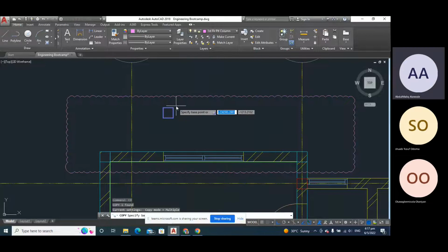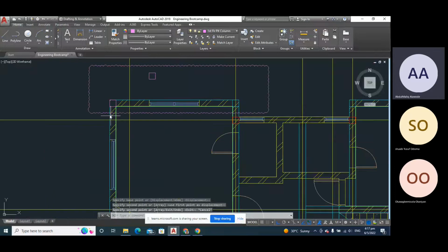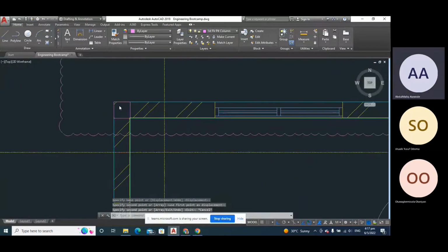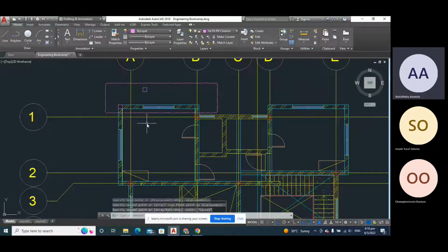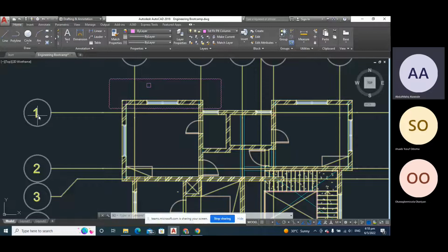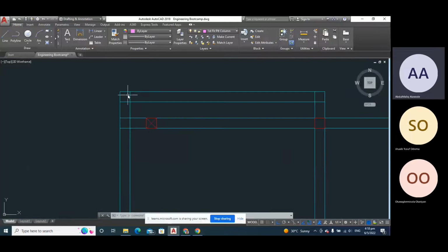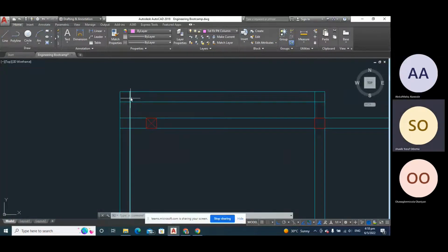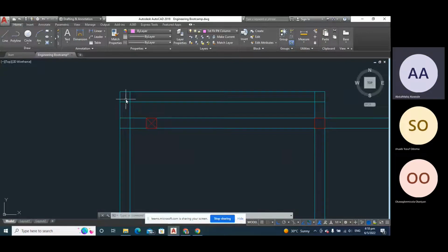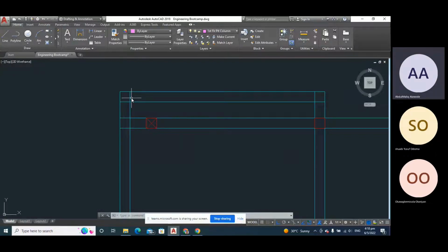Okay. So we are taking this point as our first reference point to plant our column. So what we are doing now is this column, this grid line 1 prime. This point is grid line 1 prime, A prime. That means we are planting this here. Do you understand me? Yeah. So that means the column I've just fixed now, that I placed on the beam there, is going to be at this point on the first floor. You understand the gist now?